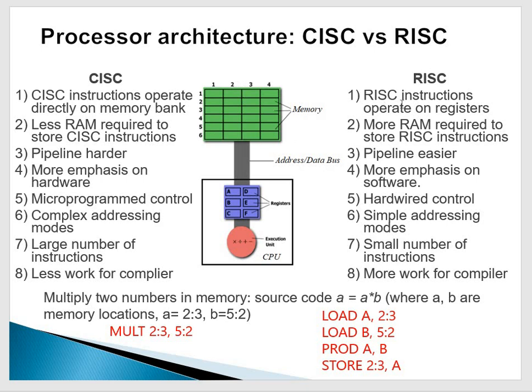On the other hand, in case of RISC, if we want to perform the similar operation, the first feature of RISC is that RISC instructions cannot operate directly from the memory. They can operate on the registers only.